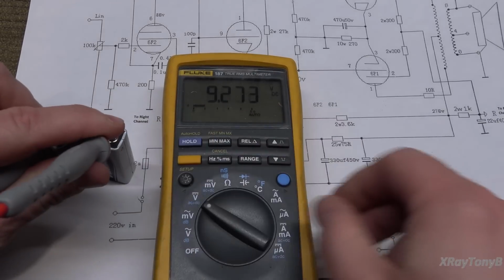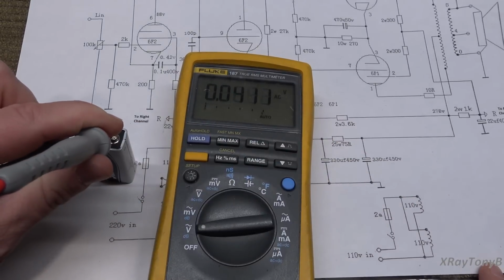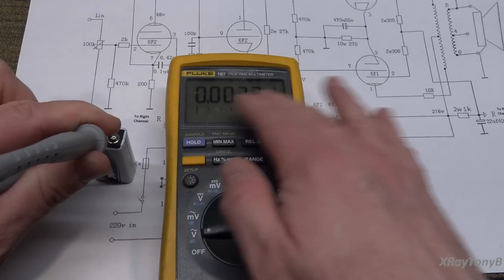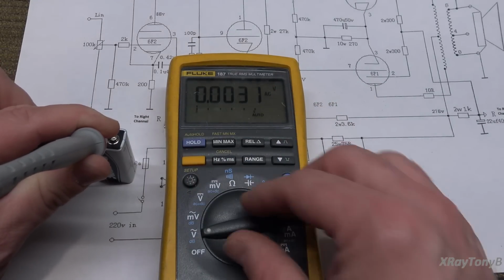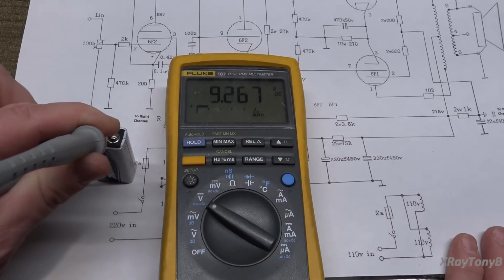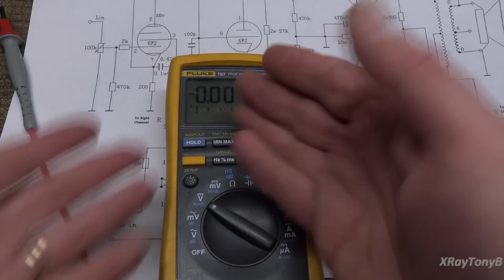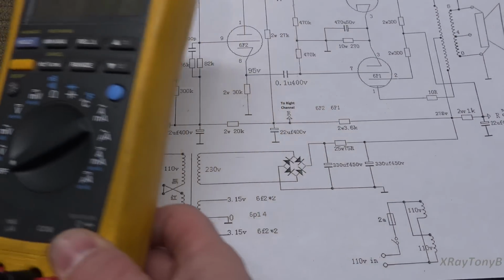And as a matter of fact, if I try to measure AC voltage, it doesn't read anything. Okay, it'll pick up a little bit of noise from around here, but essentially there is nothing there because it's not alternating, it's direct. So you have to set your meter to DC to see it. Now, this is nice, it gives you a number, but it really doesn't show you what the voltage is doing, right?